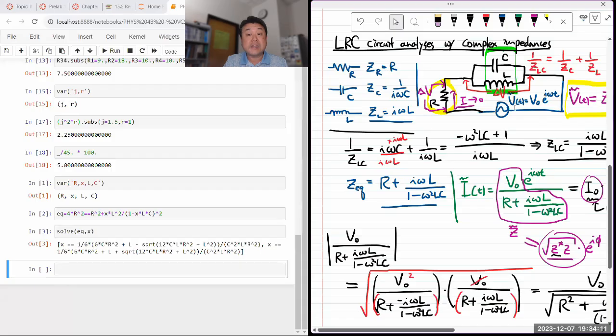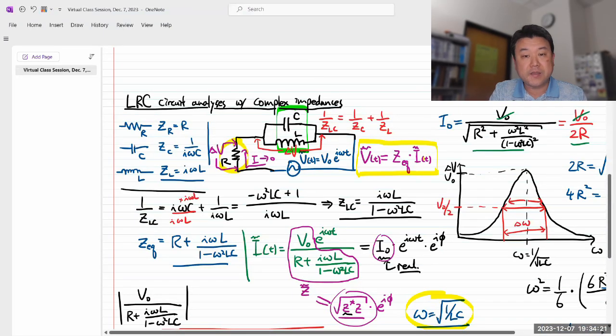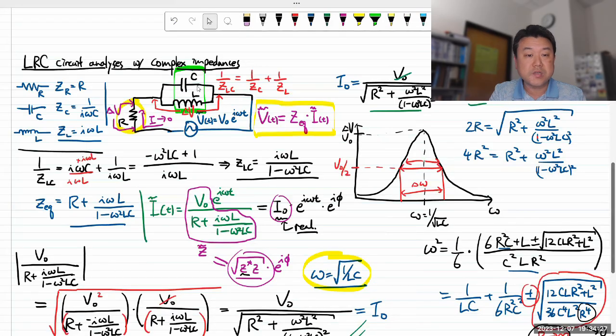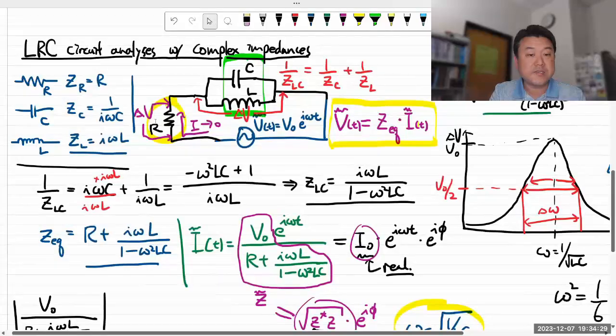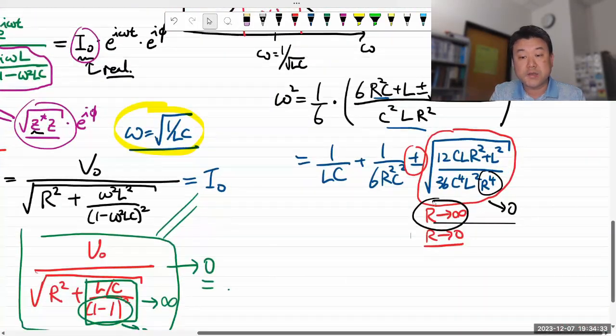So this alternative circuit, which you can only analyze using complex impedance, has that practical benefit: when you are building it in the lab with a real circuit, you can use easier values of resistances to work with. Because as you use those larger resistances, your Q factor will increase, so you will see a more prominent resonance behavior.